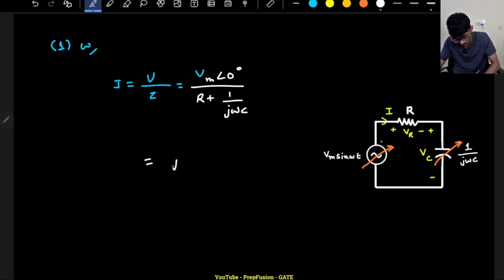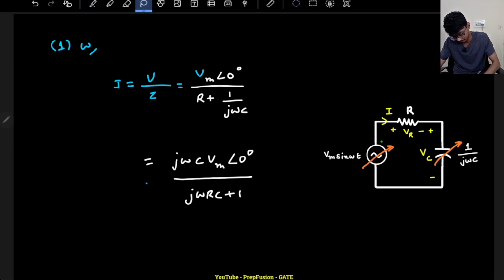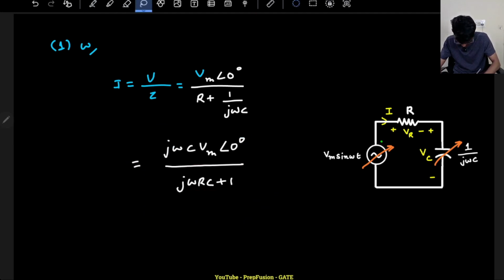So I equals Vm angle 0 times j omega C divided by 1 plus j omega RC.